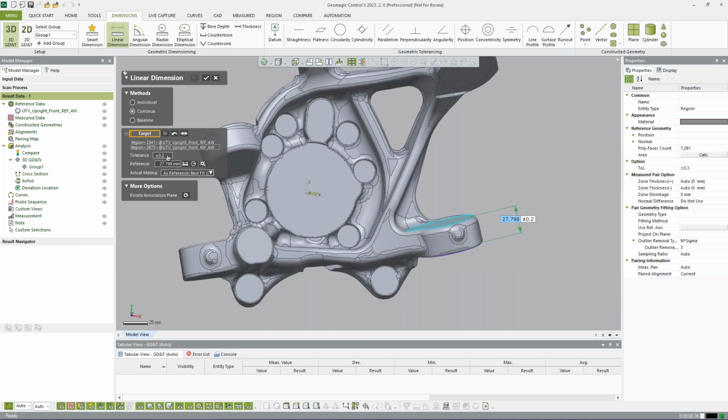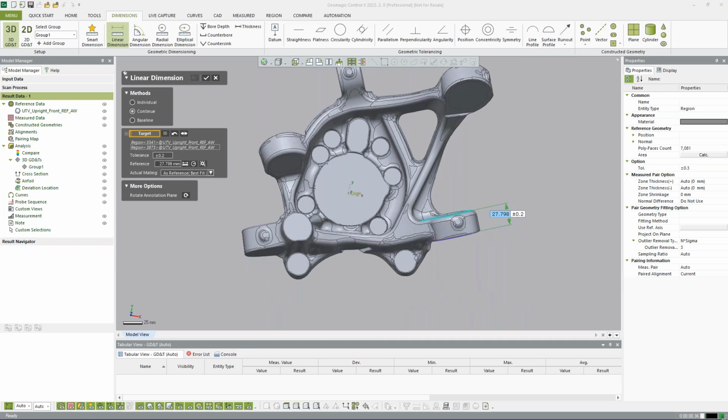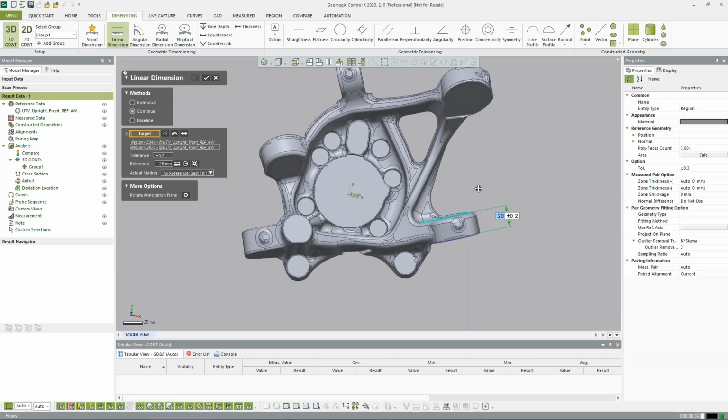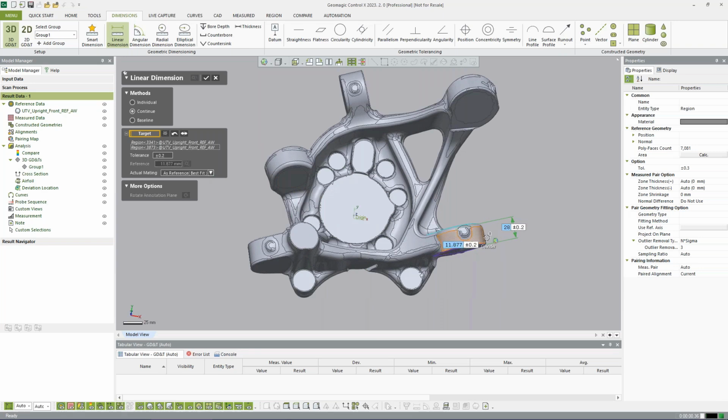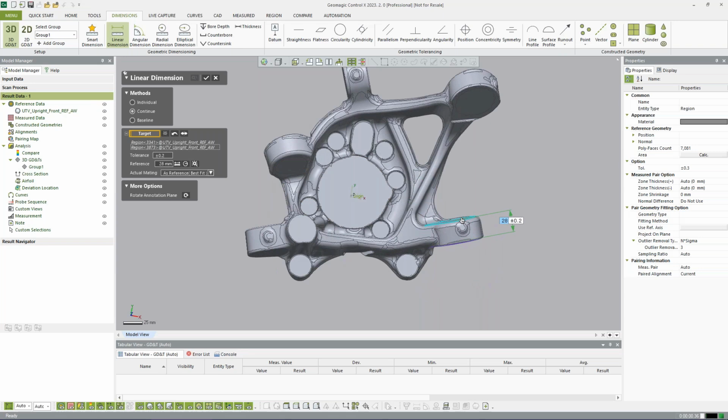And then we can come in and put some tolerance on here. Now, the other thing is this is the actual as-measured part. So it's actually 27.798 millimeters. That's probably not as designed. So if we want to, based on a print or whatever, we know this should be 28 or something like that, we can come in and override these and do a plus or minus 0.2 on them. So maybe this one was a little bit undersized, okay? And we would want to showcase that. If we think it goes the other way, maybe it should have been 27.5. We'll know in a bit.